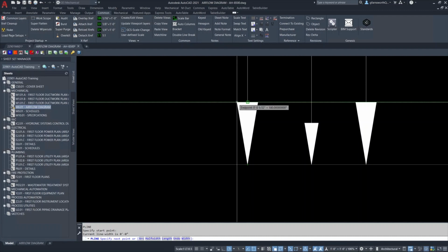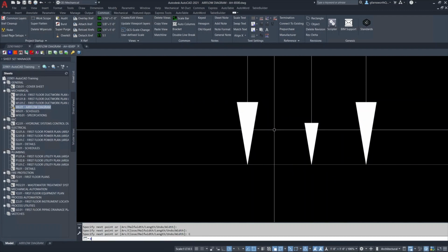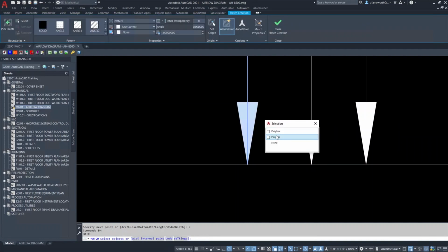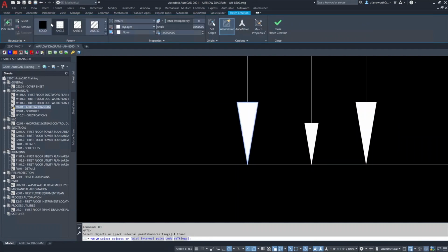In Revit, instead of an arrow, you will just see a line. The solution is to either replace the text and leader in Revit, or replace the leader arrow with a solid hatch, which Revit does understand.